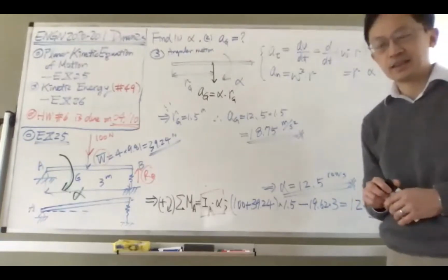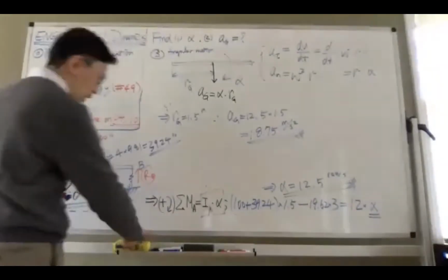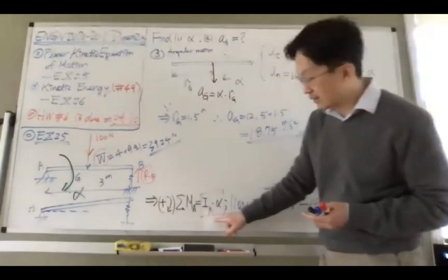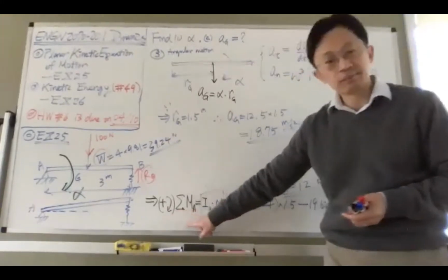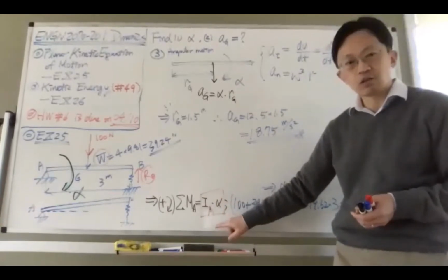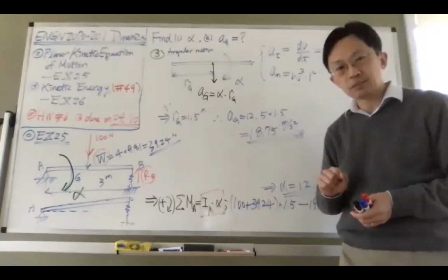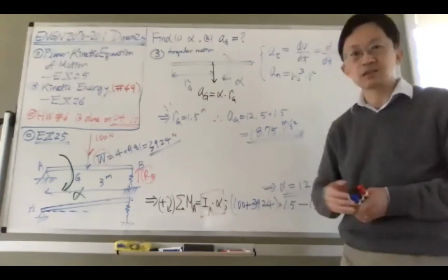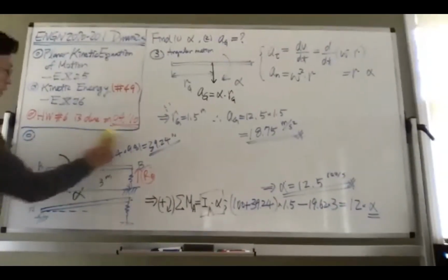All right. Any questions on this? Nope. It should be very straightforward, right? The only thing you want to pay attention to is the important concept here. For the moment equilibrium, you have to remember that on the right-hand side, if you choose to use the mass moment of inertia at the center of gravity, you always have three terms. But if you choose to use the mass moment of inertia at the center of rotation, it will reduce to just one term. And the fundamental reason is because of the parallel axis theorem. This is the most important point in this example.